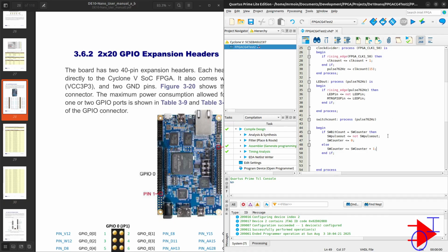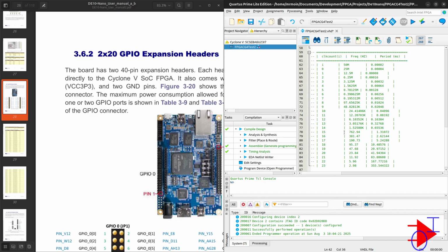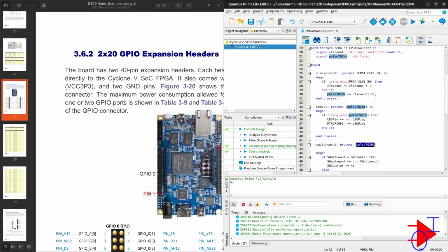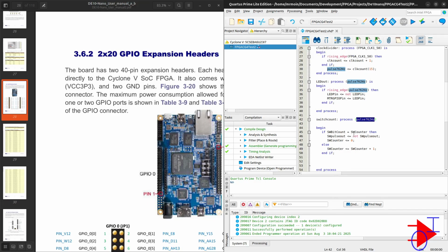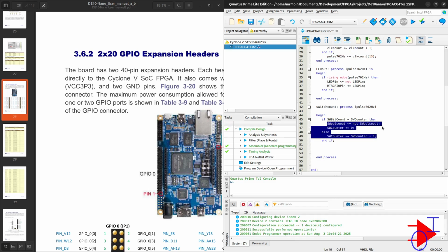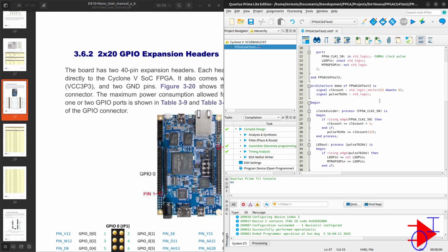Okay, so when it's equal to the counter, we're going to send the pulse out, and we are going to reset the counter. If not, we're just going to increase the counter. Basically, that's as simple as it is. So essentially, every time this pulse comes in, we can slow this down even further. I think 15 was, yeah, it's 762. So 762 hertz pulse comes in, we match it against our process counter, and if it's equal, we reset our process counter and send out a second pulse, and this pulse will be used by our LED and our motor.